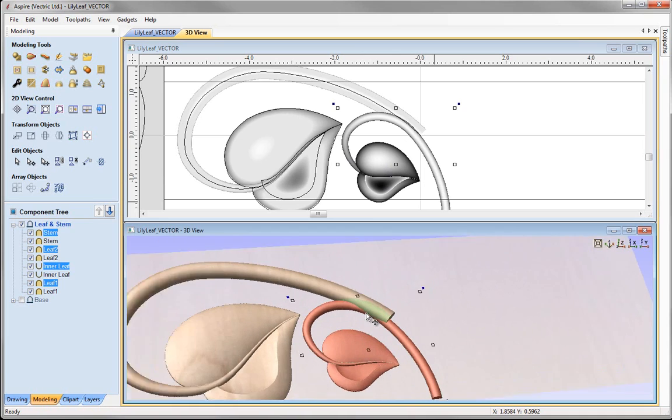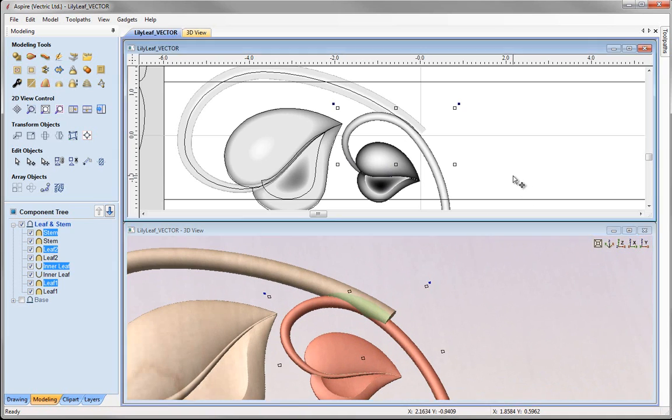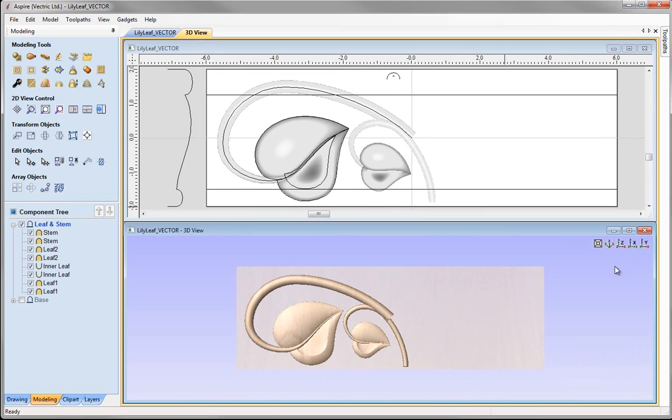And if we look at the 3D view, we can see that's coming right in there, so I'm happy with that. Then we'll just press F to fit that to screen, look at that down Z. And then ultimately what we want to do is create a mirrored copy of these two components on the other side. So I need to look at removing this smaller stem area here, as I don't need that.